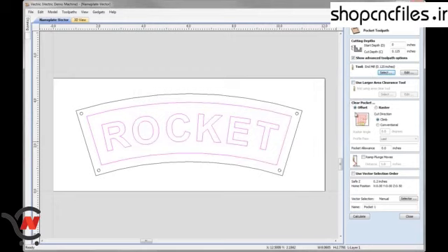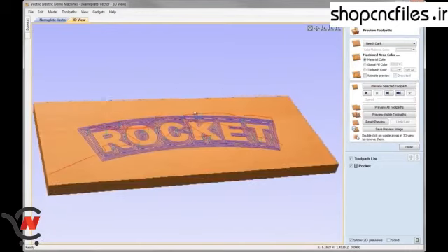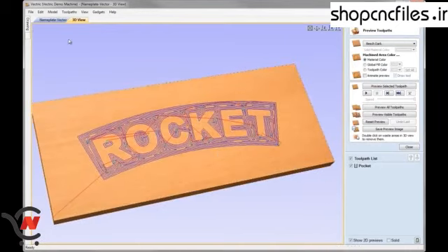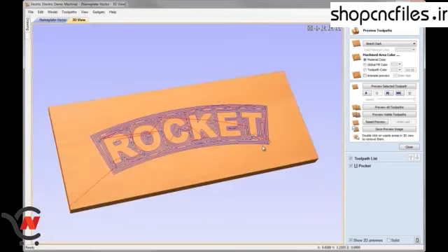I'm going to do an offset toolpath in this case. I think I could also do a raster pattern if I wanted, and we'll just call that toolpath pocket and go ahead and hit calculate. So there we can see the toolpath drawn for me in the 3D view. Automatically the software's gone from the 2D to the 3D view here to show me that toolpath, and it started the preview toolpath menu here.